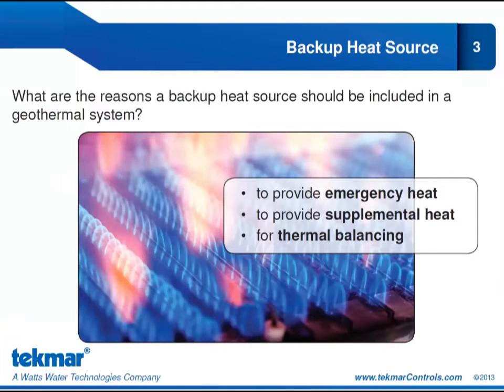Now there aren't many of those days, so our heat pump is still going to be used for most of the time, almost all of the time, and we can reserve the operation of our backup heat source for those very cold days when our heat pump and earth loop just can't keep up to demand. The other time when we're considering supplemental heat is if we have distribution loads that require high temperature water. So perhaps we have some loads that exceed the capacity of our heat pump. They require water that is at a higher temperature than our heat pump can provide due to its operational limits. So that's another time when we would consider supplemental heat.